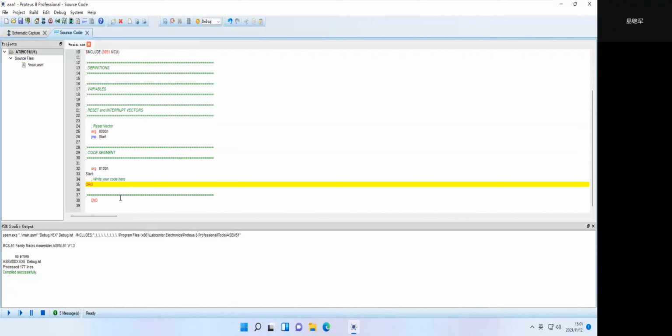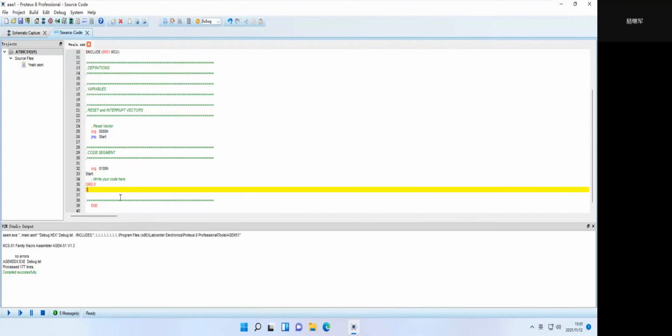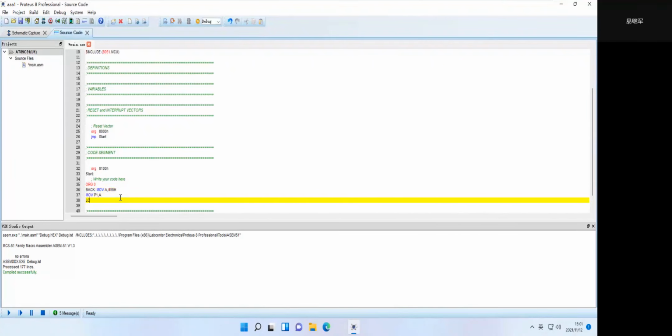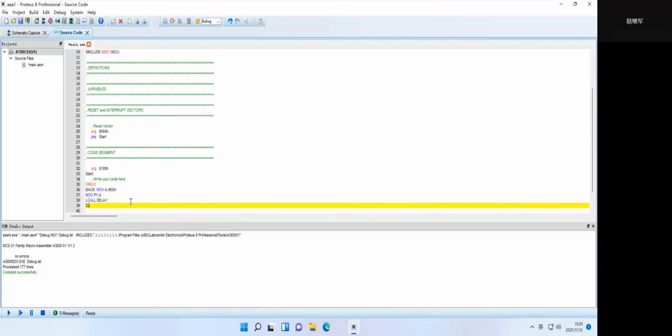ORG 0. MOV A, #55H. MOV P1, A. LCALL delay. SJMP back.